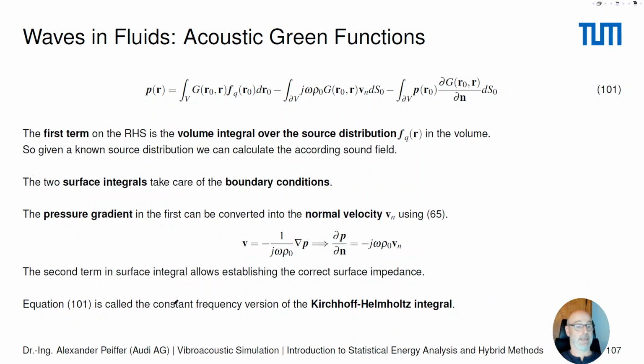Good. So anyhow, there's a naming convention. This equation here is called the constant frequency version of the Kirchhoff-Helmholtz integral. Wow, a lot of mathematics, but don't be completely disturbed. When it comes to practical applications, things become much clearer. Just one final remark. This equation here is what is normally used in the boundary element solution. If this is used with discrete meshes, this is what we call a boundary element solution, because if we don't have any terms here, we just have to use discretization of the boundary by using those two surface integrals.